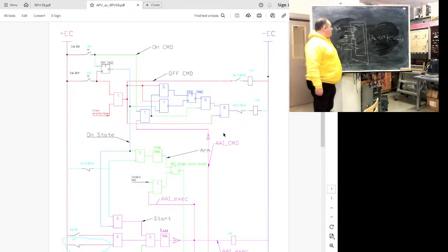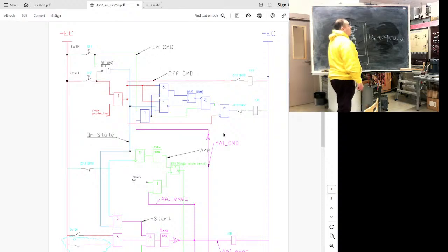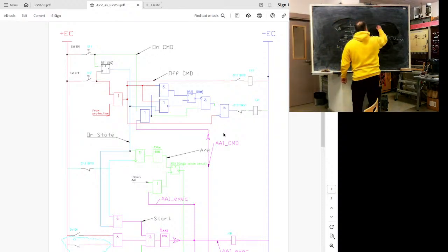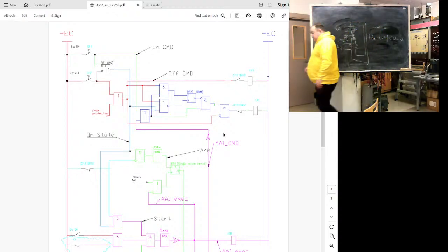Usually with this relay, if voltages are 100 volts, it operates in a range of approximately 10 to 20 degrees. It can be adjusted.